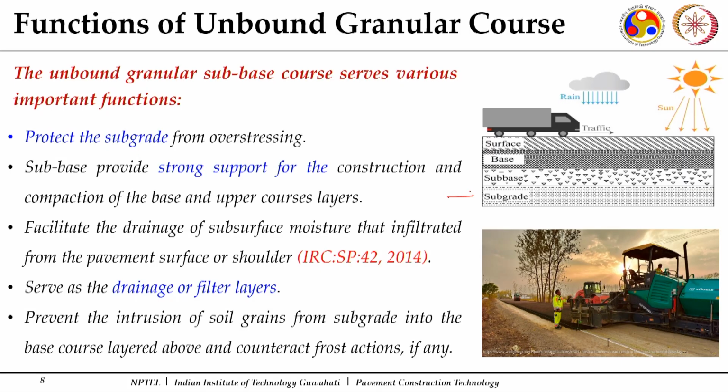If I mention here, this is my compacted subgrade followed by a sub base, which is most likely to be in an unbound state, a granular course. Then you have a base course, and on the top you have a wearing or surface course. This sub base course has an open gradation. It protects the subgrade, because the wheel load is going to get distributed over the subgrade. So, it adds to the strength of your pavement crust. It protects the subgrade from overstressing.